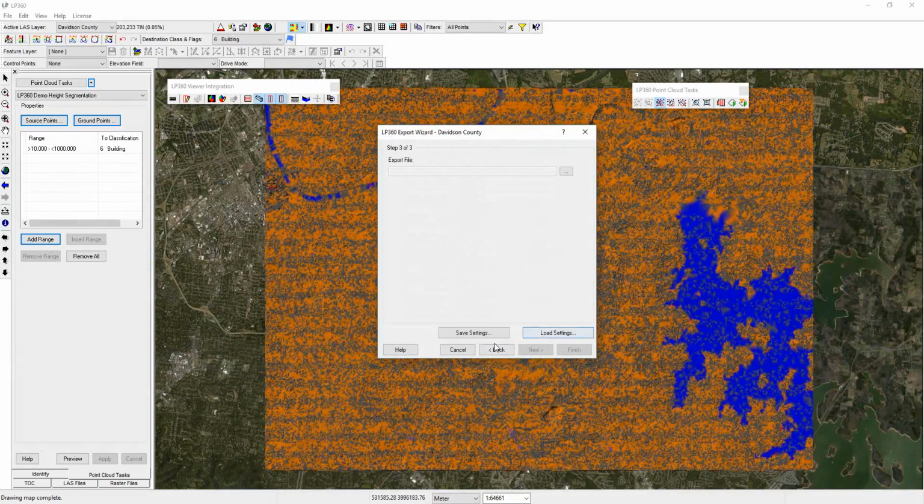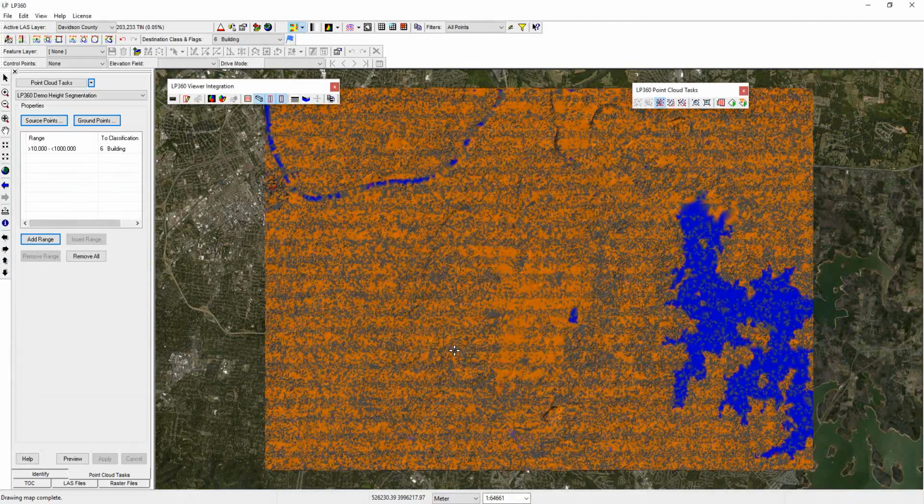So there are ways, once you've got your data set where it is, or you've got the area of your project site where it is, that you can then output surfaces, output contours, output DTMs, DEMs, the point cloud. If you just need to segregate the point cloud, you want a smaller LAS file, all sorts of ways that you can push the data out if you need to for some downstream work, or as a deliverable to a